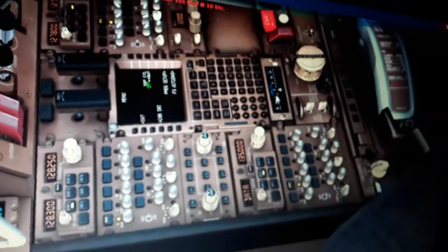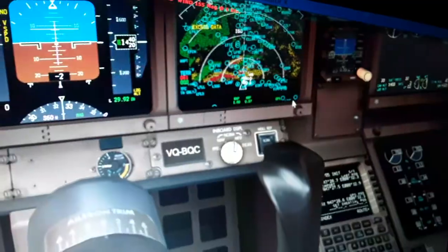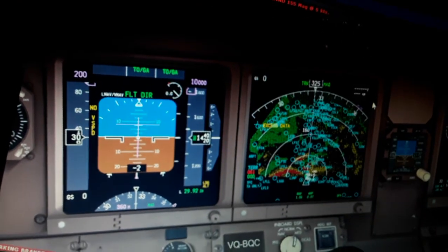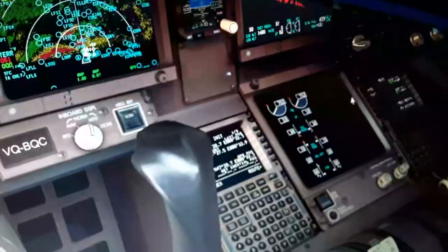We have many radios, some are communication, some are navigation. So we have the ILS localizer displayed with the ILS localizer frequency, but it's tuned automatically using the flight management computer inputs, using our aircraft calculations for takeoff. We also use the departure runway and departure airport, and the arrival runway and airport and pictures for arrival for ILS localizer arrival. For instance, everything is tuned from the flight management computer. We only need to set up the autopilot panel. So we set up the panel like that.